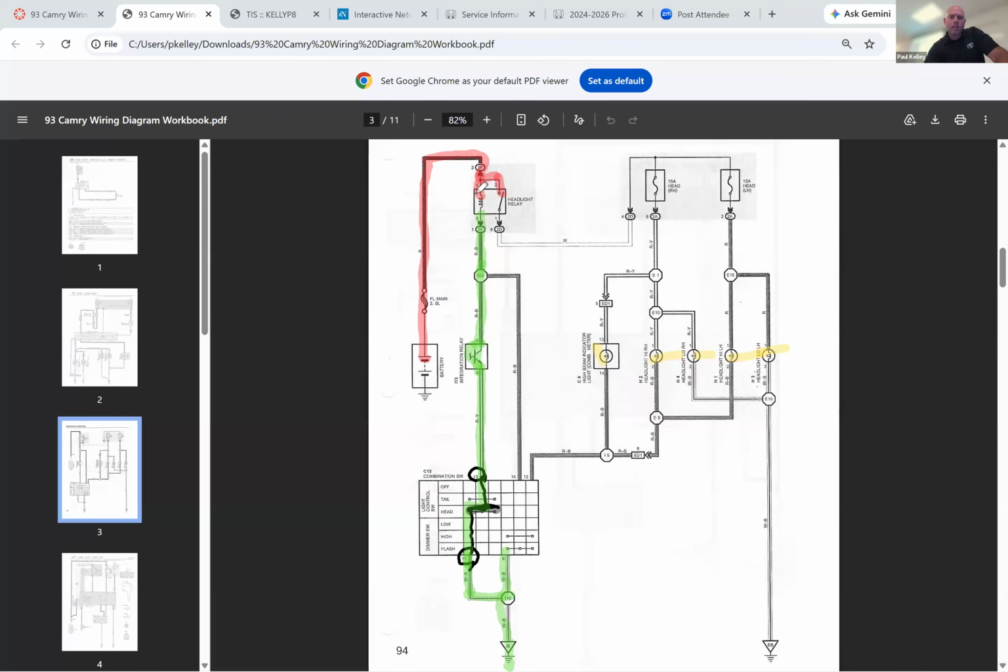Now, if I've got red here and green here, what happens to that magnetic relay coil? It magnetizes, right? Which is going to pull this over. Now this is connected. So if that's connected, now we can go with red coming down, over, up, over, goes here, goes here, and so on.